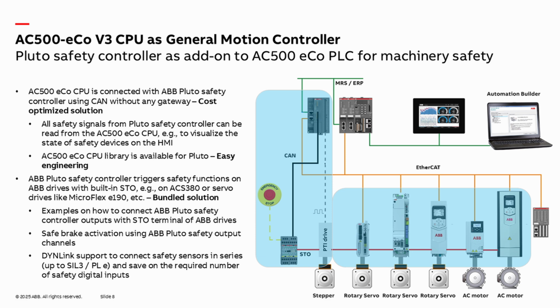In addition to that, and you'll hear that in the next slides, Pluto Safety Controller brings also very nice features like DIN link, where you can connect safety sensors in a ring and then connect it to just one safety input. So you optimize on safety input number, and also the multi-master principle to communicate between different safety controllers, and then even have some redundancy, which will be again covered. So this solution has also unique benefits.